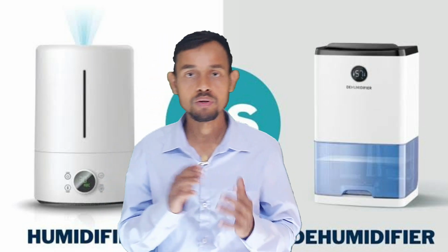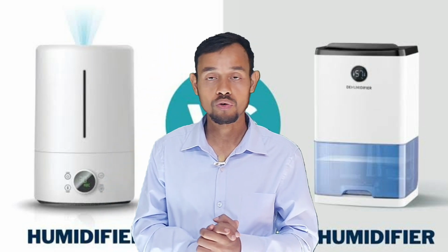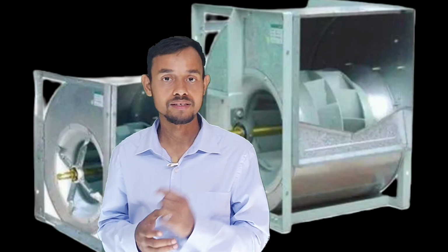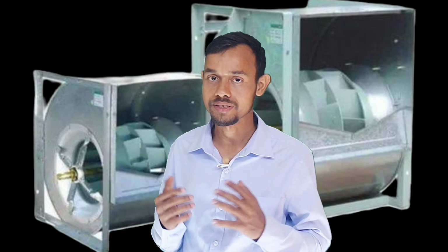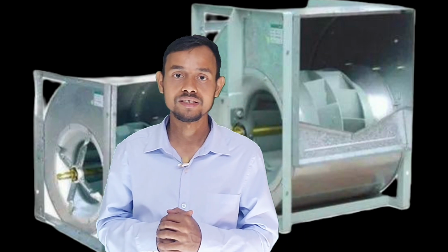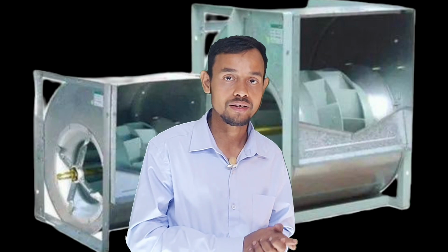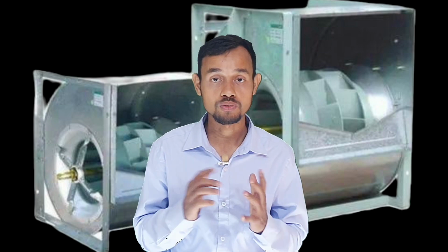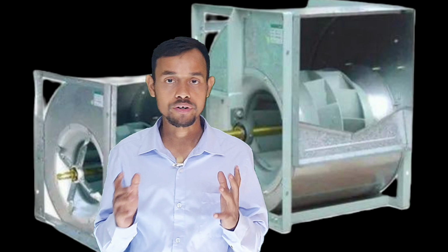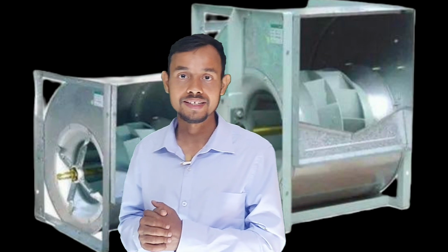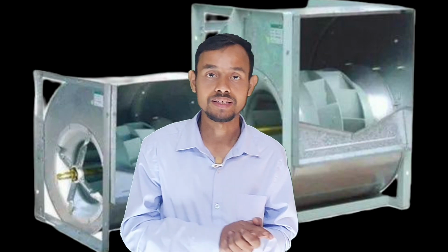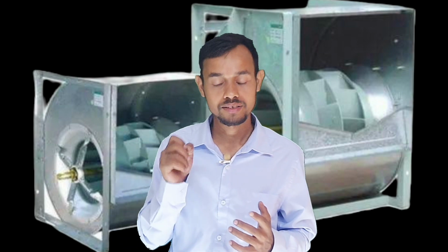The blower in the AHU produces a lot of noise that gets transmitted to the office spaces through ductwork. As a result, sound attenuators are installed in the AHU to reduce the noise. Vibration isolators are flexible devices that absorb vibration. These are mounted between the blower and the AHU casing to absorb the vibration created by the blower.